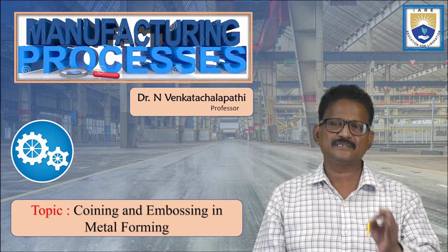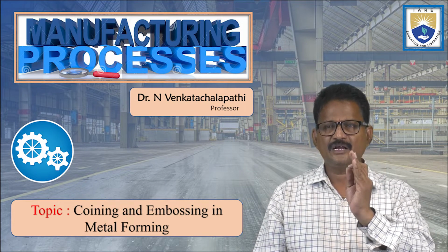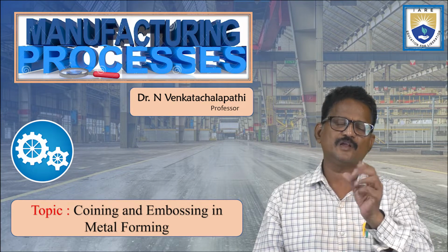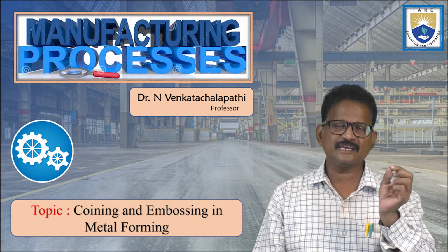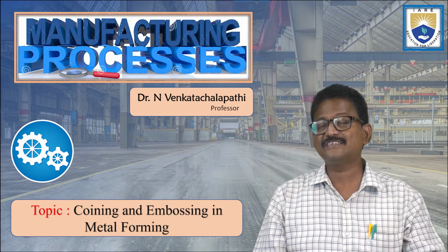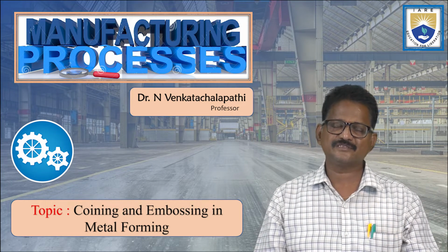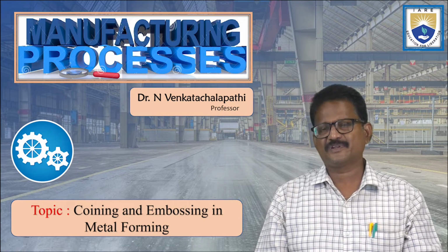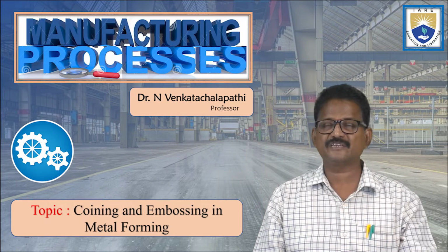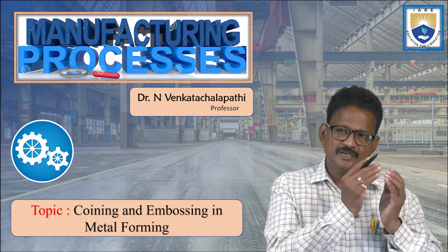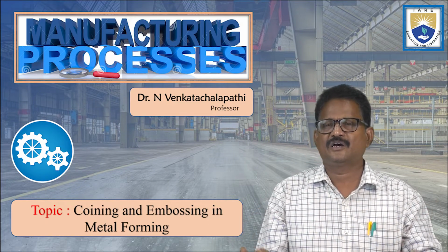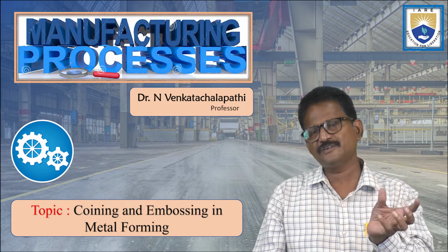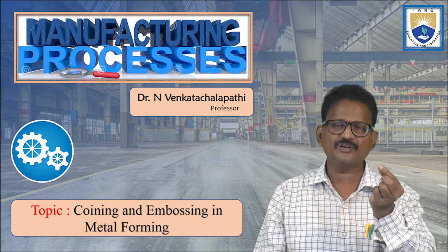Here we can heat and apply pressure or force, giving some cooling time and solidification time so that the final object can be formed. But the major difference between metal casting and metal forming is that in metal casting a lot of wastage occurs. There are so many step-by-step processes like pattern making, pattern design, mold making, mold preparation, and molten metal. It is a tedious process. But in metal forming, whatever amount of raw material is taken, the same amount of final component is received. So if 1 ton of raw material is utilized, the same tonnage of output can be obtained, depending upon the product.